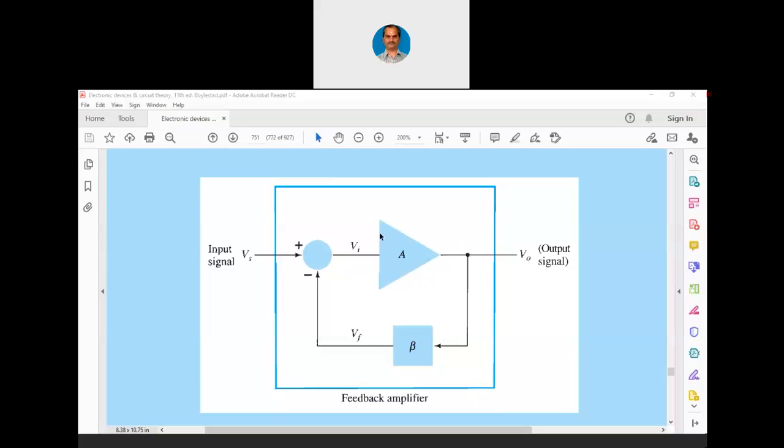That is the indication here. When the input signal is coming, it will see a wall here, which simply means that the amplifier is not going to take any of the input signal's energy into it. If the amplifier uses the energy of the input signal, then the input signal, which is already weak, will become weaker. So the amplifier should have a very high input impedance such that only the signal enters the amplifier.